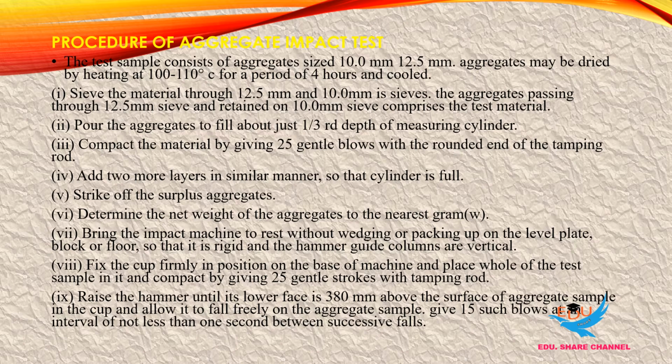9. Raise the hammer until its lower face is 380 mm above the surface of the aggregate sample in the cup and allow it to fall freely on the aggregate sample. Give 15 such blows at an interval of not less than 1 second between successive falls.